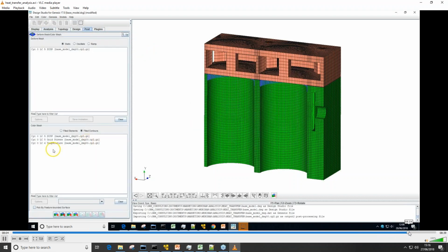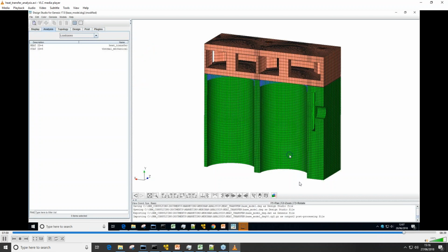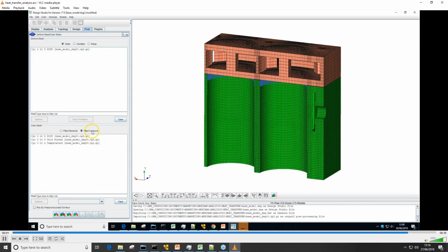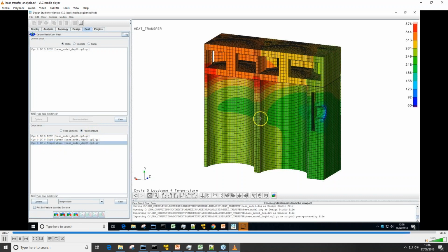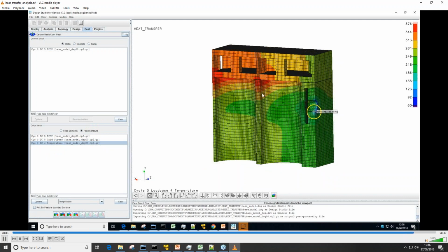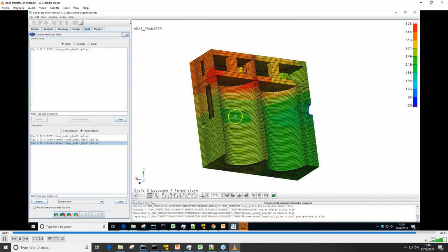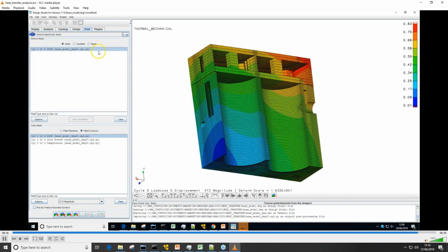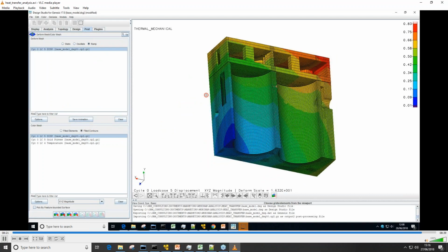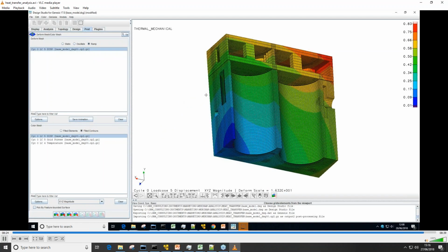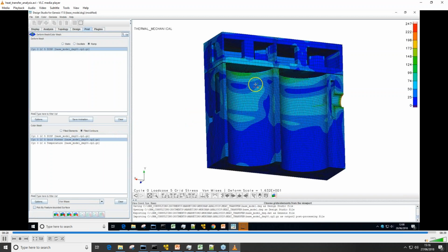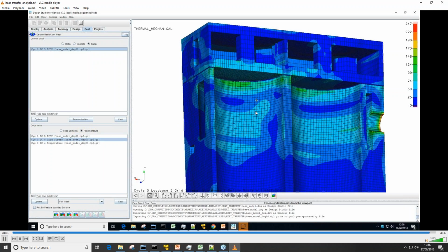And then finally, just take ourselves to the results data set. Once it's solved, you've got your temperature distributions, which you can see. Having run this model, I think it's perhaps a little bit hot for an engine. We're up into the 300s of degrees, so the boundary conditions perhaps aren't the most demonstrative, but it's proving the point very well. And you can see the expansion of the engine block example. And then we can interrogate the stresses applied to that engine block due to the thermal expansion.